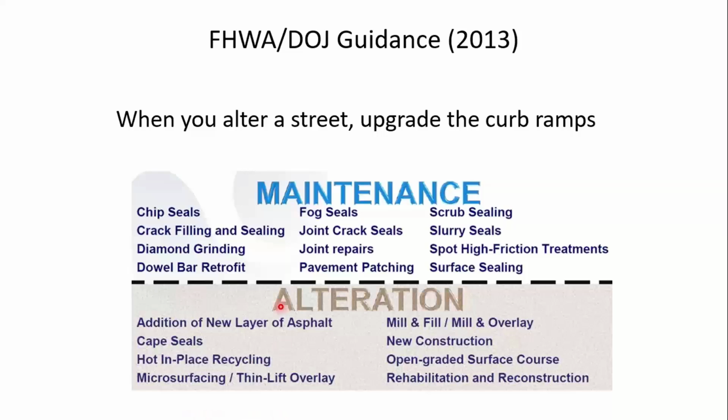So you'll notice there's a heavy dashed line through the center of the slide here. If what you do to your road or street is an activity that falls above that line, it's considered maintenance and you don't have to touch the curb ramps. So for example, pavement patching. Probably any entity with roads does pothole patching or pavement patching. That's maintenance. Crack filling and sealing, I'd call that a pavement preservation technique.